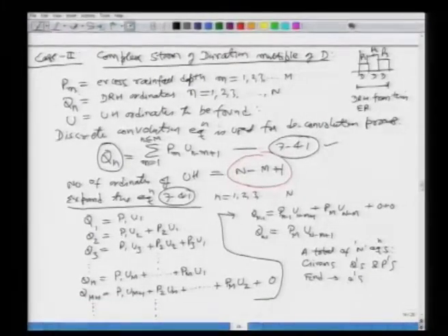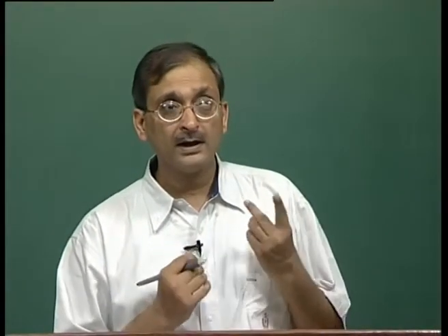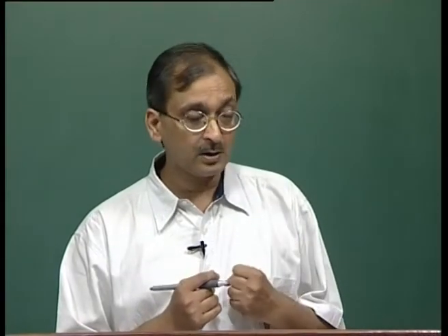So, let us move on. This can be done in many ways, in fact, that is determination of the unit hydrograph ordinates given the rainfall and direct runoff hydrograph data. But we are going to look at two methods, and the first one of them is called the method of successive substitution. So, let us look at that.